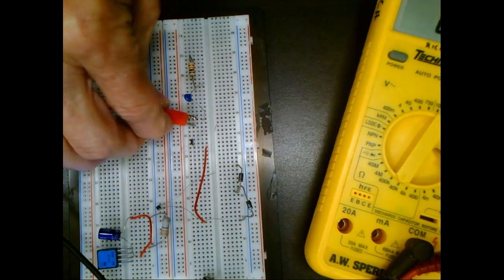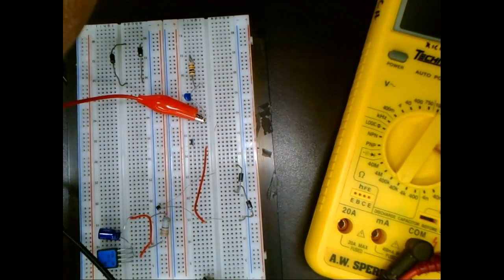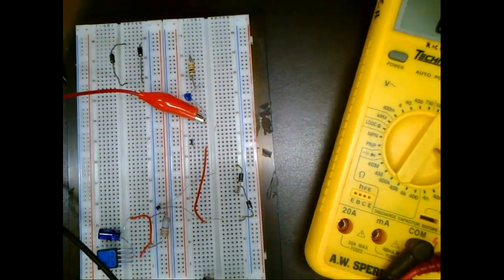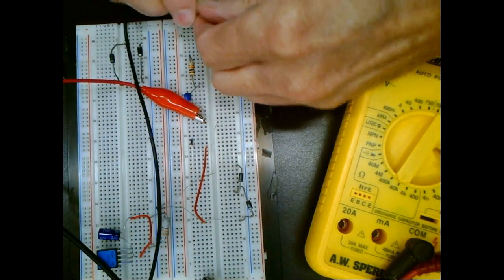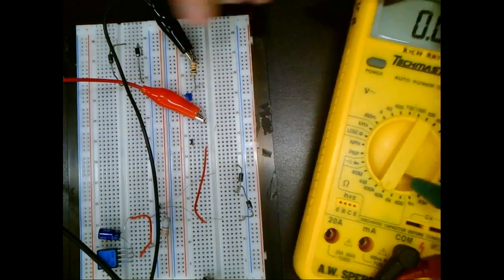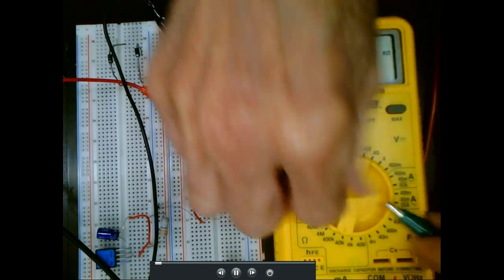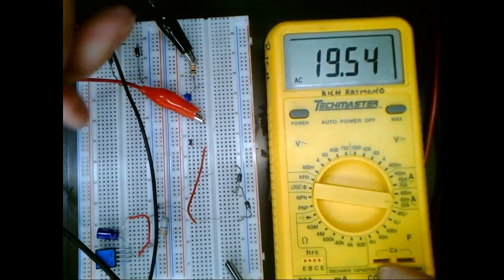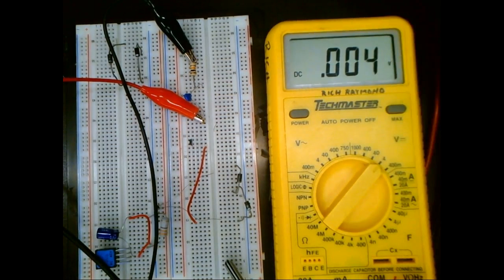And we'll put the positive on the top. And where did my other lead go? And we're going to put it across the 5-volt supply, so that way I won't have to adjust it. Put my common down at the bottom. And then I'll set my meters up. Set my meter up to measure what? Volts. Probably 4 volts would be okay. Okay.